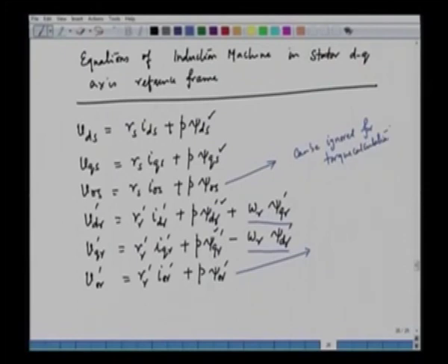And furthermore, the zero sequence components do not have any coupling with either D axis or Q axis. If you ignore that particular equation, you do not need i0r anywhere. We do not need i0s anywhere. So since i0s and i0r are not required in the equations for the calculation of torque or otherwise, we can avoid the computation of zero sequence currents in the stator as well as in the rotor. Now why then do we show them in the equation form?